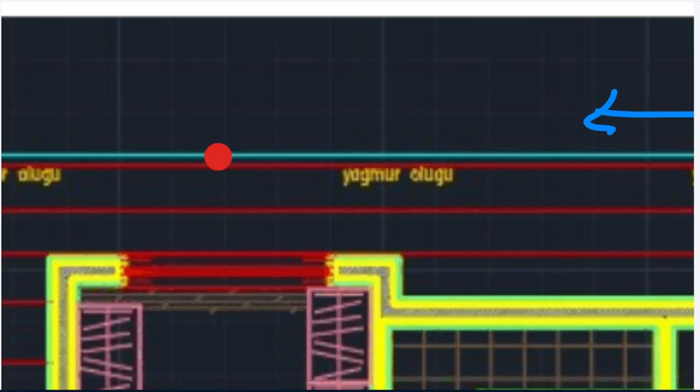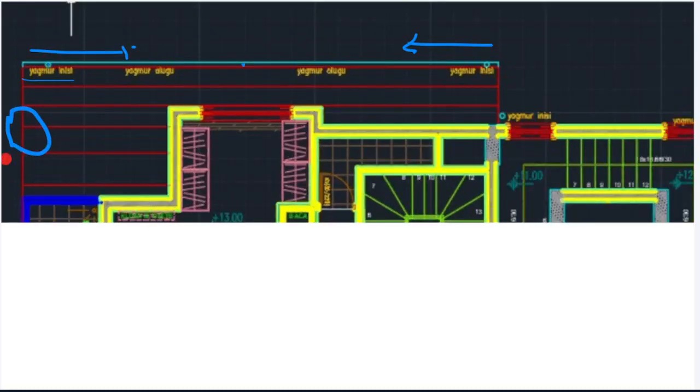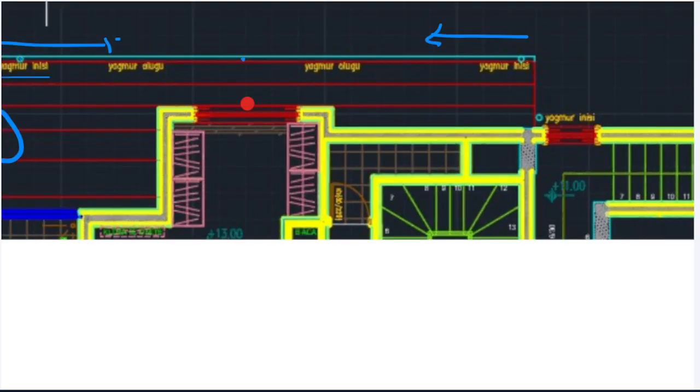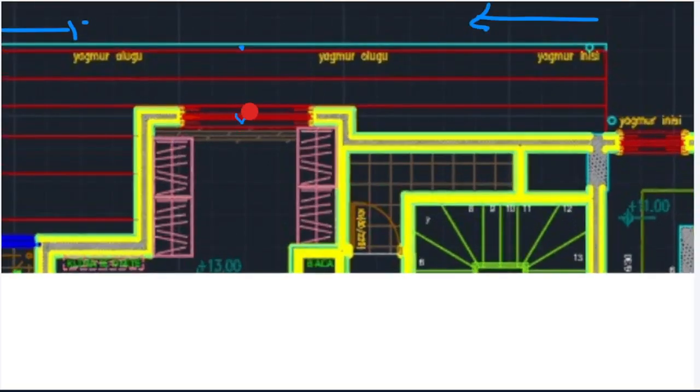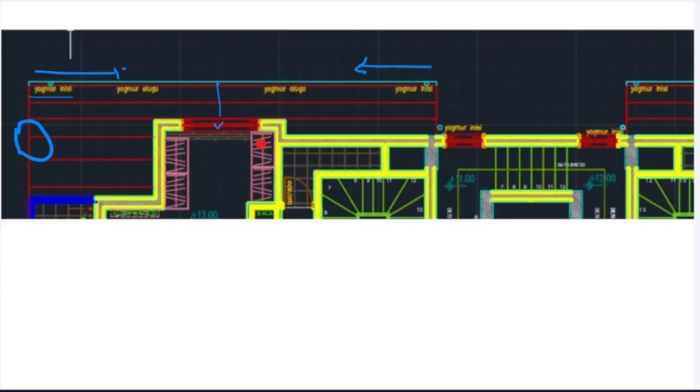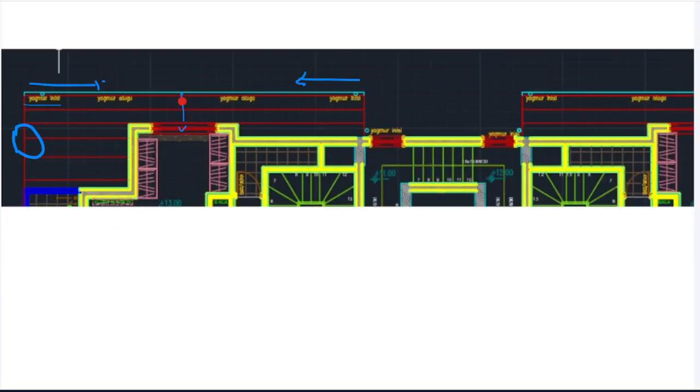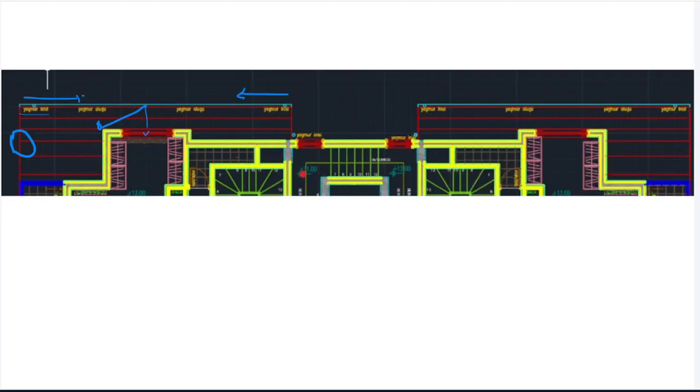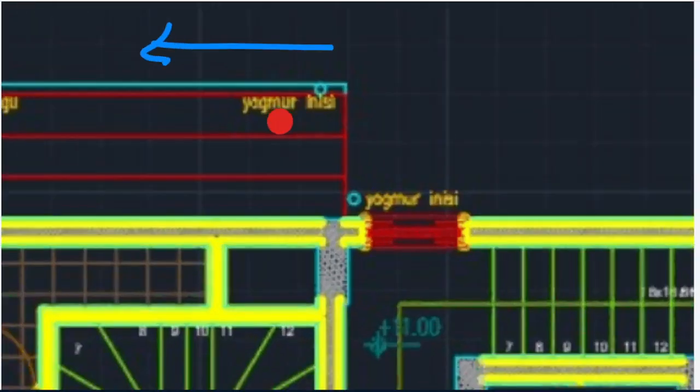And do you know what is the reason that they didn't put a gutter here? Hocam, on the facade, on the elevation, is in front of the maybe windows. Yes, Berlin, I will give you 5 points. Look at here. There's a window here. So if you put a gutter, all the facade, you have to put a pipe. Unless you move from here to here, and here put another pipe to go to the bottom, which will be ugly. That's why always try to put the pipes somewhere else, write the information, write 10 centimeter gutter.